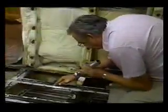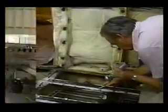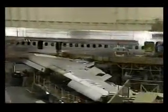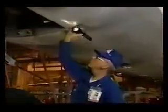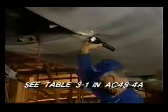This section is devoted to common aircraft metals, coatings, and their corrosion products. The primary metal used in manufacturing aircraft skin is aluminum alloy sheeting called Alclad, or simply clad. Although clad is highly resistant to corrosion, pitting can occur if inspection and routine maintenance are not performed. Other metals commonly used in aircraft construction require special preventive measures to protect them from corrosion. The information which follows summarizes Table 3-1 of your AC 43-4A.